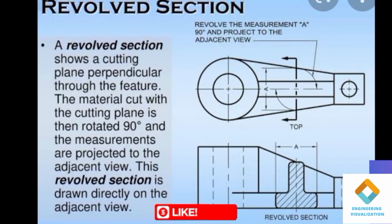You can see in the revolved section, a cutting plane is cutting exactly perpendicular to the feature in the material, and it is rotated exactly 90 degrees and projected as an adjacent view. You can see clearly in the diagram, the revolved section has been cut and revolved at exactly 90 degrees and shown as an adjacent view. You can see the same thing in the diagram below.